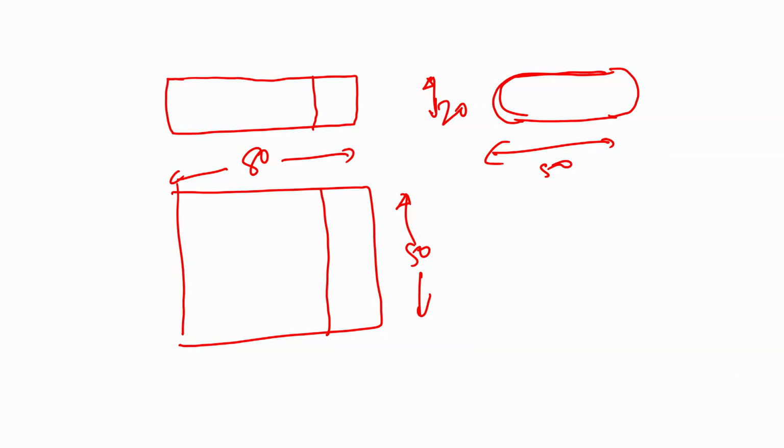Next comes how do I produce this radius. So I need to show here what this radius is. So I indicate here saying approximately it is 10 millimeters. It is fairly complete, because normally it is understood what it is, and further, often people show the center here, they show the center line, sometimes they show the center distance, but it will be redundant if I put 10 here and 50. So R is equal to 10 and all that, this is sufficient for me.